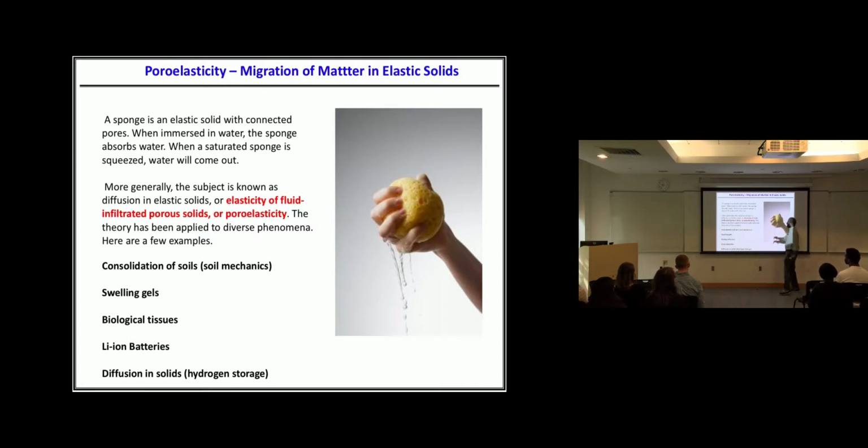Now, when you take this sponge soaked with water and squeeze it, meaning you apply compressive stress, fluid flows out. These fluid-filled solids are what we call poroelastic materials. Remember, the solid is still linear elastic. There is no viscosity, though it can be viscous too, but that's an idealization.